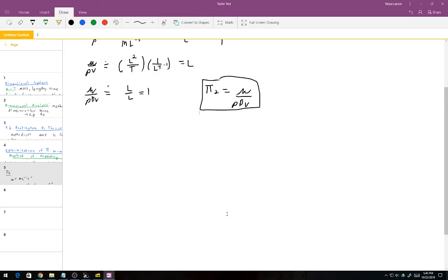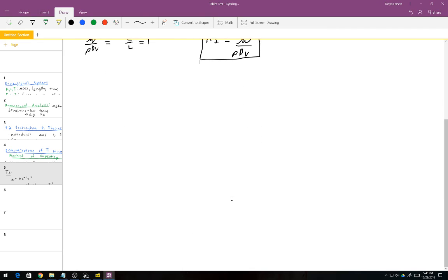So what this comes down to is a relationship. I'm going to use these two pi terms to investigate my problem. Instead of running an experiment with many, many different variables, many different pipe diameters, all of that, I'm going to look at just these two pi terms and compare them in relation to each other, and find a function relating them through a very simple experiment.